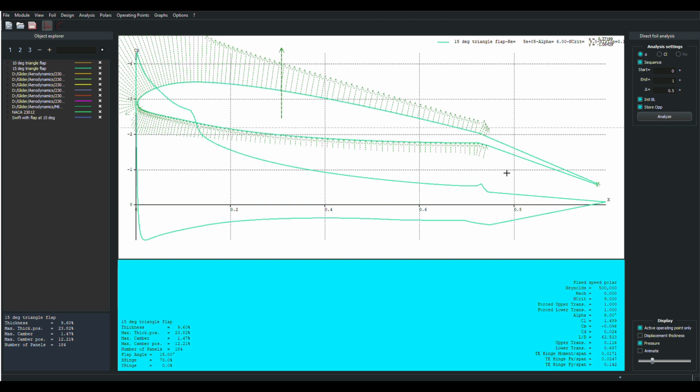And then I'm going to use duct tape to hold it to the trailing edge of the current wing. So I'll have about a 1/2 inch of thickness there. It'll stick up above and slightly below the current trailing edge. It'll protrude into the flow. And I'm actually going to take some pinking shears and cut some V-notches into the duct tape to see if we can trip the flow and get even more deflection.